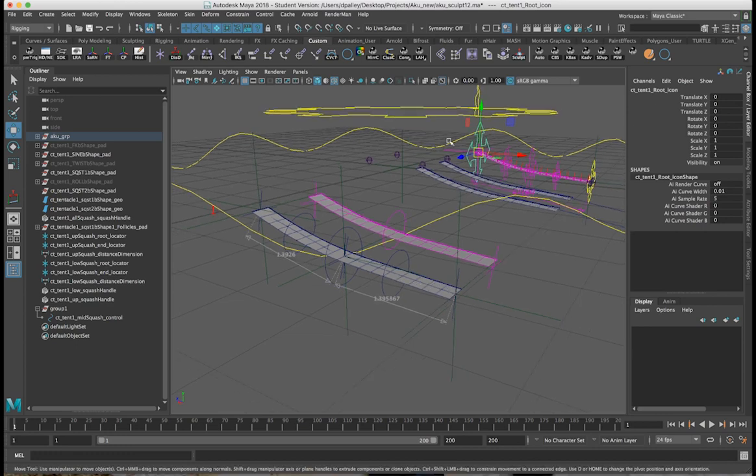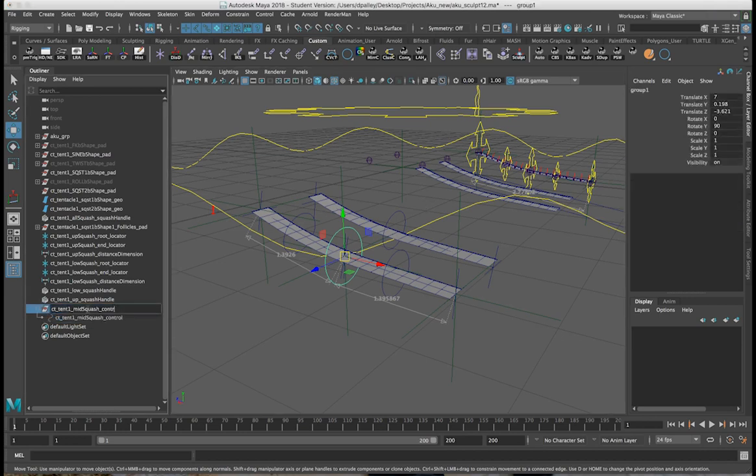That way if an animator wants to select all the binding controls or all the main controls in the rig, they can use the underscore icon. Anything I'm going to use as a reference, like on a blend shape rig or something like that, I always use control, just so that I don't mix them up. And I'll just call this control pad.